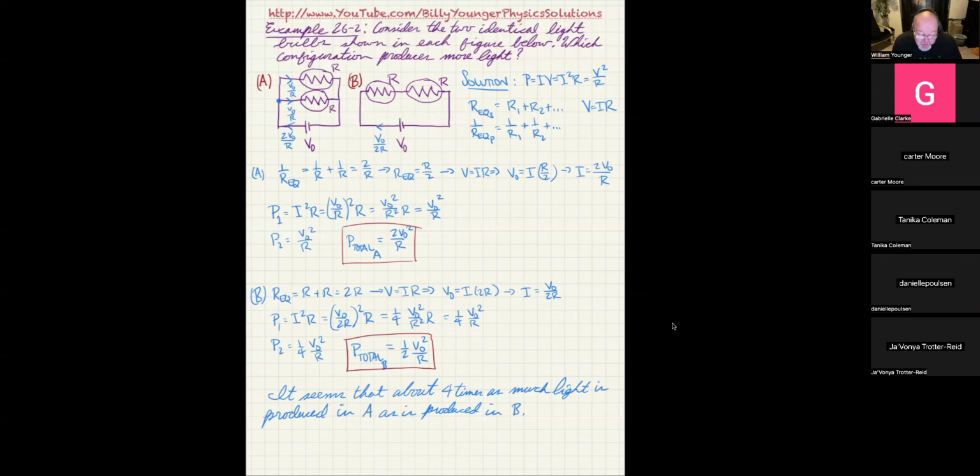Whereas if you had it in configuration A, what would ultimately happen is the one light bulb that died will, of course, go black, but being an open circuit, it's not going to allow any current through it. So all the current can go straight through the other light bulb. So the other light bulb will still be working and be a little bit brighter. Any questions on that?